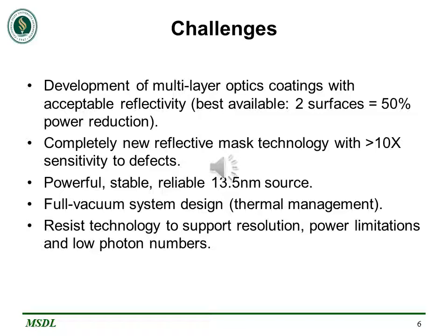We would also need a source that could reliably and powerfully give a wavelength of 13.5 nanometers. The system needs to have a full vacuum design, and the resist technology should have good resolution and shouldn't have any power limitations and low photon numbers.